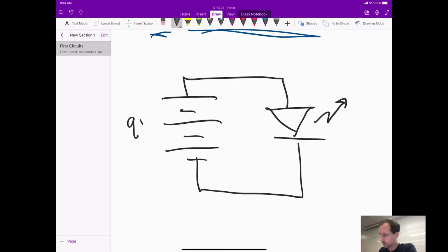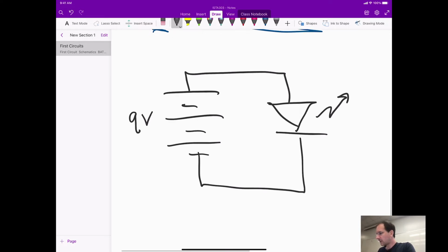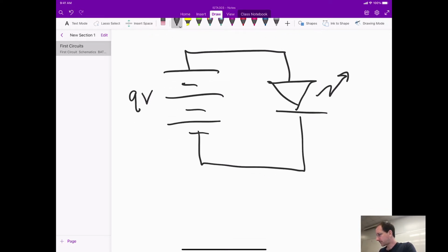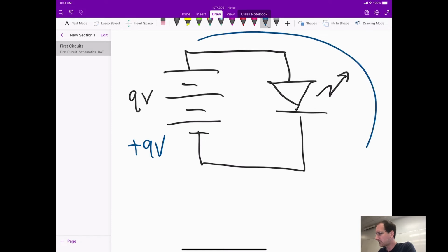And so let's say that's 9 volts. So we're using a 9-volt battery, and we know that's generating 9 volts. That's sort of given to us. And so we know by Kirchhoff's voltage loop law that the rest of the circuit must use 9 volts as well in order to satisfy this criterion.